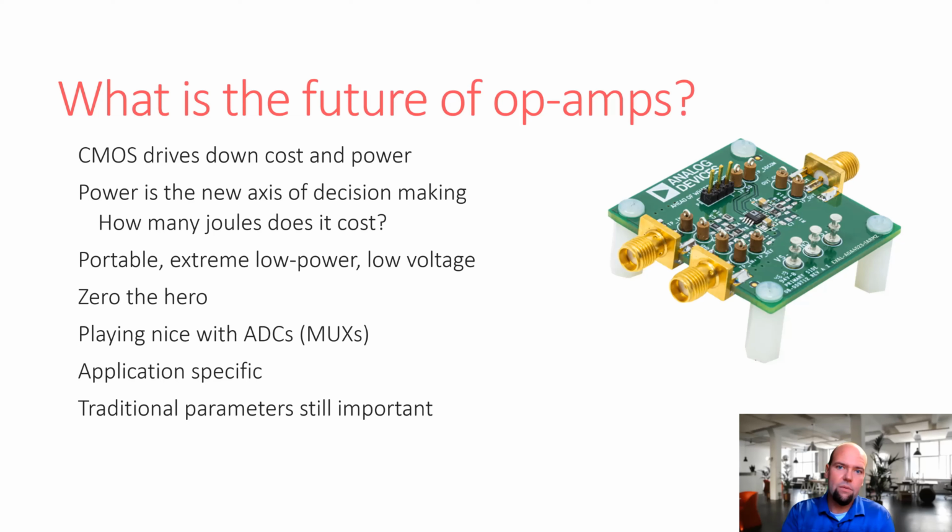So as you step on it, you compress the load cell, and the strain gauge picks up that strain. That strain is a resistance. It shows up as a change in resistance. And so you have to have a circuit that takes that change in resistance and converts it to something a microcontroller can read.